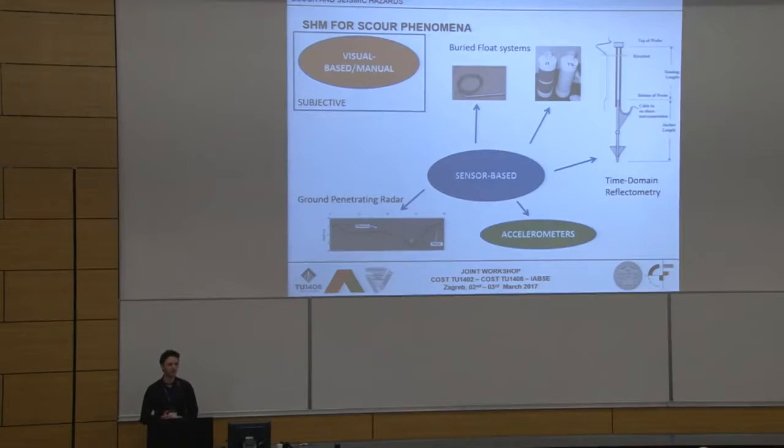So for Scour, the structural health monitoring is broadly similar in the sense of the vibration-based aspect, which I'll discuss subsequently. But aside from that, the most common way that Scour is assessed still internationally today is by visual assessment. So divers physically go down into the waterway and they assess what the condition of foundations are and look for damage elements. It's highly subjective. The rating schemes can be quite variable, and they depend a lot on the different agencies that are implementing them.